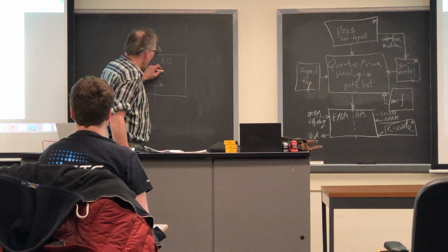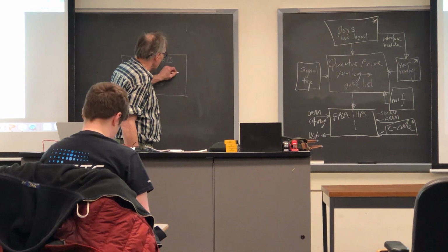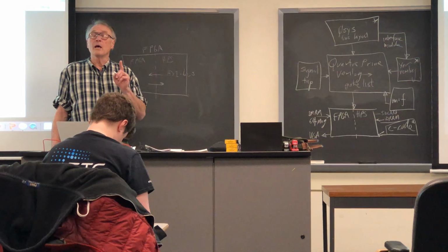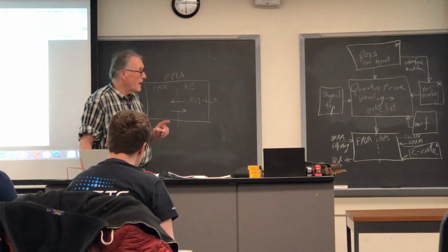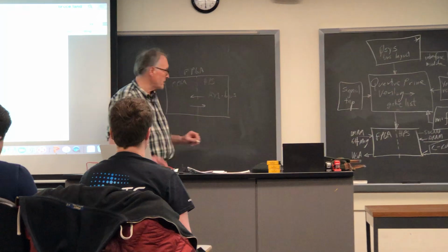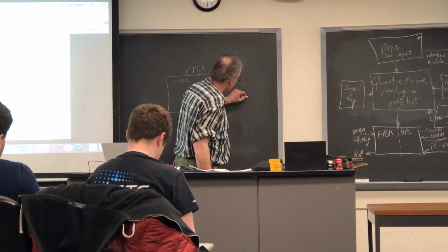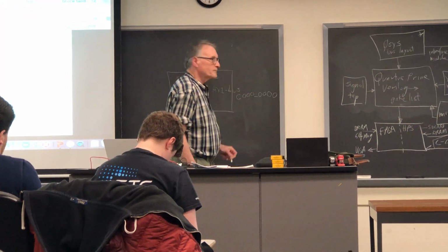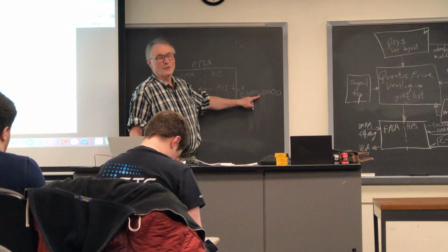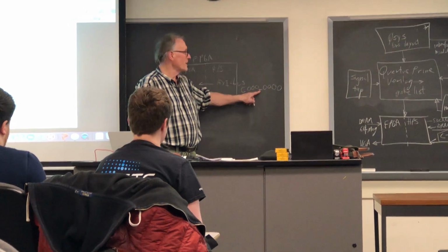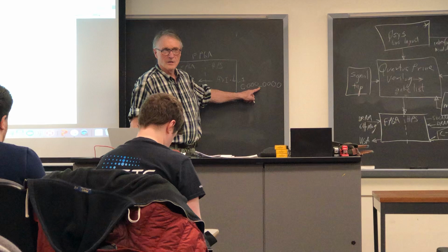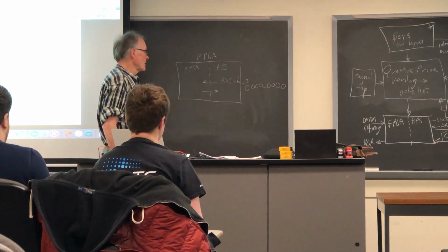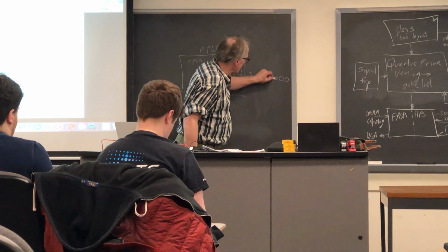There's the normal AXI bus, which on the HPS side has a hard fixed address of C000_0000. Now, in Verilog, you can put in the underscore because Verilog ignores underscores in the middle of numbers. In C, you can't do that.